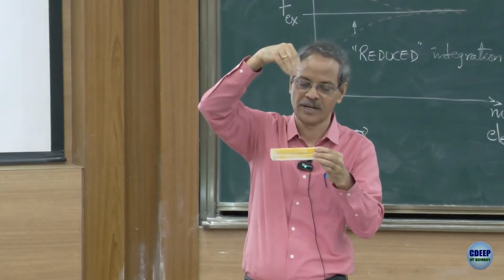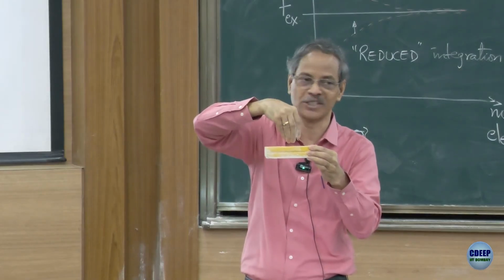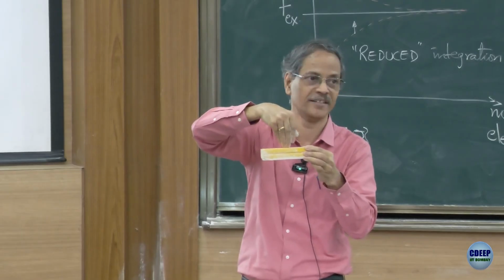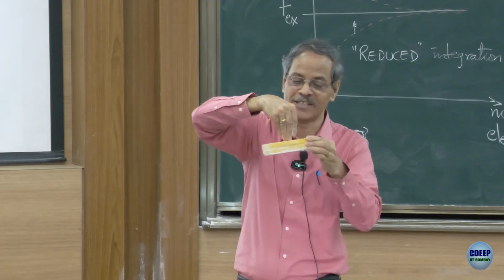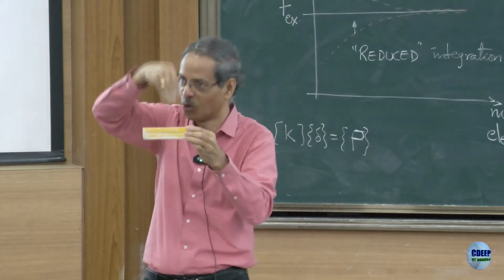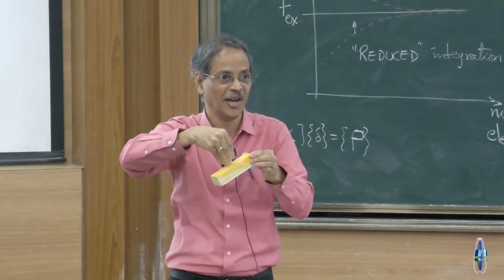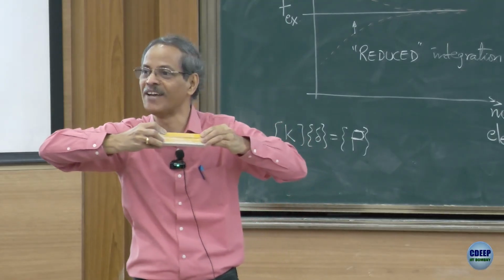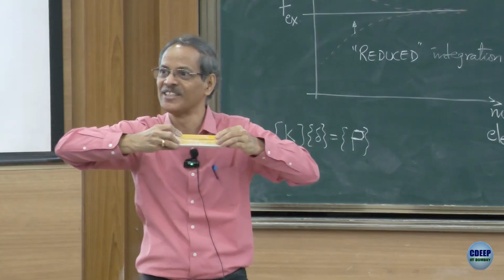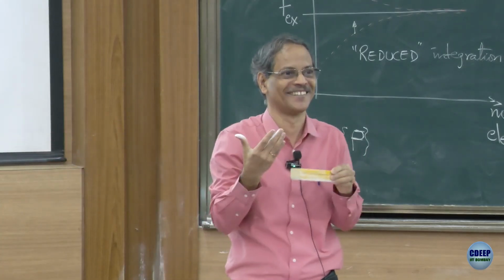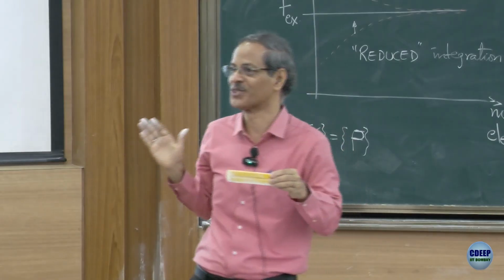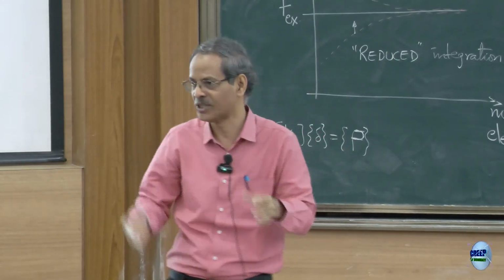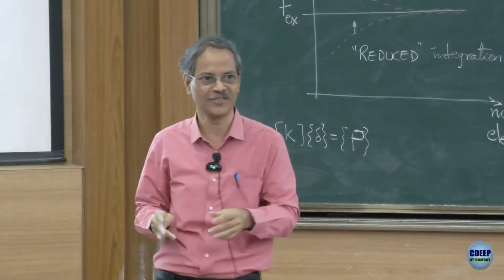Now, there are gas pressures acting on the turbine blade, which are transferred to the blade. The blade tends to deflect because of this load, but because of this force that is tending to pull it away, the blade is actually stiffer than without the force. If there is no force, you can try out this experiment after the class with your friends.